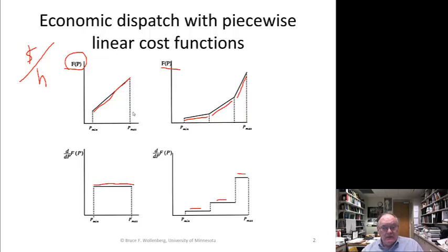These two functions are very useful for doing the economic dispatch and the costing calculations quickly. If you have a number of generators and they all have just a single linear cost function or a single number for the incremental cost, then you just rank them lowest to highest and start adding up power until you reach your total generation.